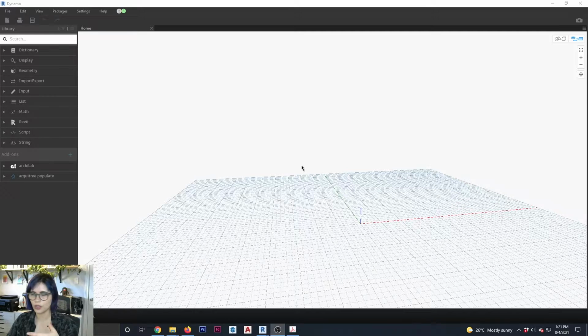You have the classic movement types. Remember, you basically have two screens overlaying each other. You have your graphic view navigation, which is your script screen, and you have your 3D preview screen. By default, you start on this script screen, and here you can zoom in, zoom out, and pan. Wheel forward, we don't have anything, so we're not seeing anything happen. Wheel forward to zoom in, wheel backwards to zoom out, and pressing the wheel to pan.